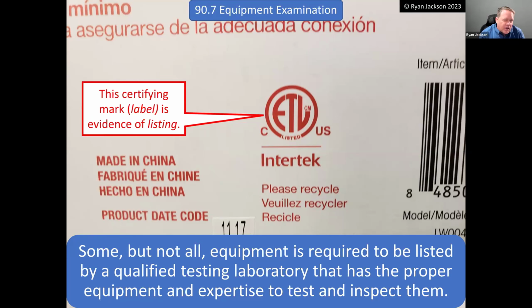In the NEC, it's not quite that way. Some stuff does, other stuff does not. So here I have the mark of a certifying body. This one is Intertek. Could be UL, could be Intertek, it could be TUV and MetLabs and QPS and CSA. There's a million of them, right? We don't have to use any particular one, and sometimes you don't have to use any of them.